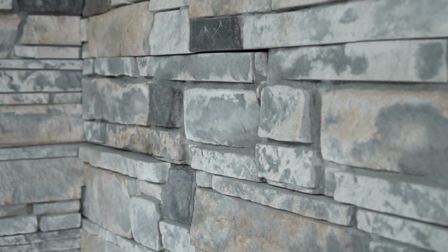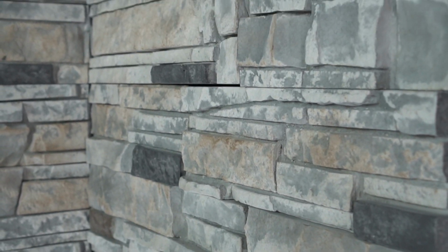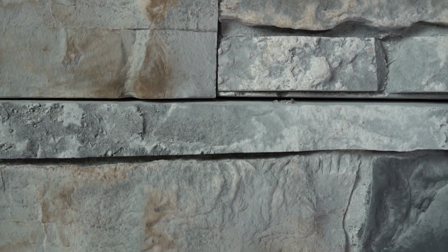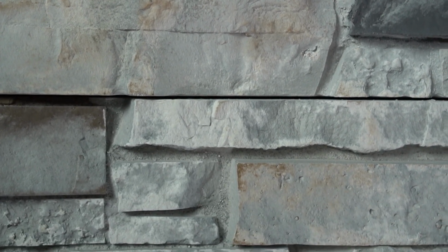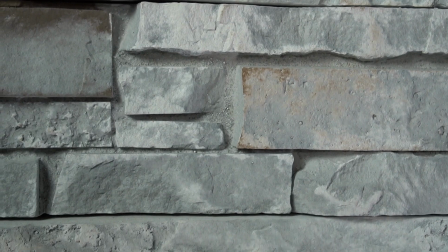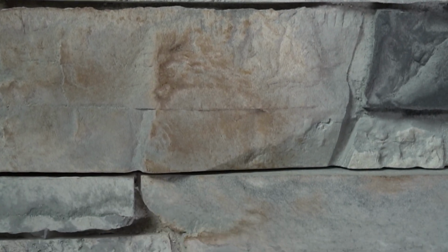When selecting stones to cut, keep in mind where the cut will be facing and what the cut end will butt against. Consider how the seam will look from all directions. Avoid corners, focal points, and facing high traffic sight lines for the cut end. It is recommended to choose a panel where the cut edge thickness will be about the same as or less than the thickness of the adjacent panel material.